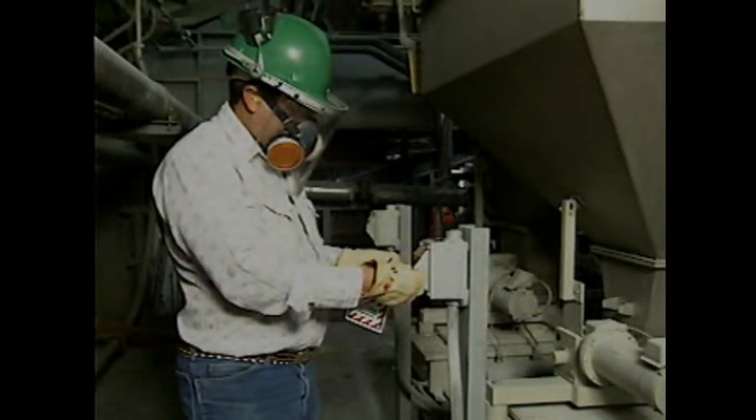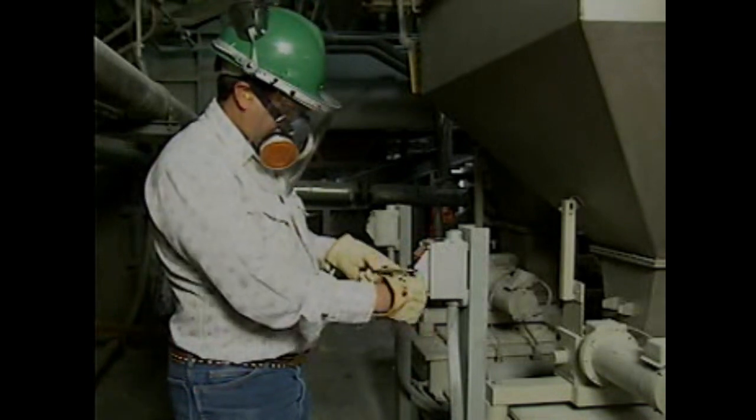This allows equipment to be locked out of service so that it can be worked on safely. Here's one type of circuit breaker that's sometimes used in electrical systems. It has an on-off switch. When the switch is in the on position, the contacts are closed and current flows through them. When the switch is in the off position, the contacts are open and current is unable to flow to the load that the breaker is protecting.